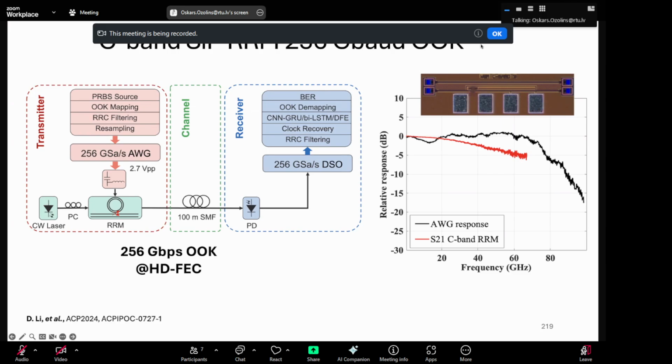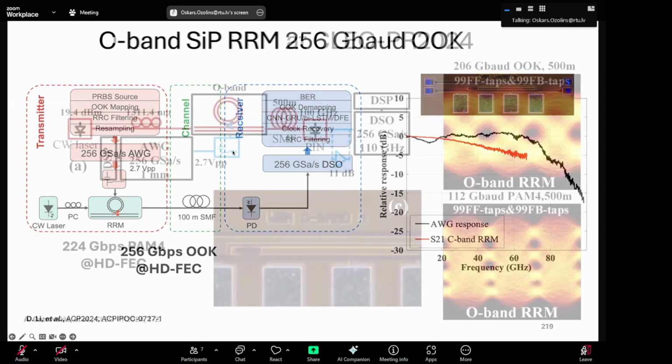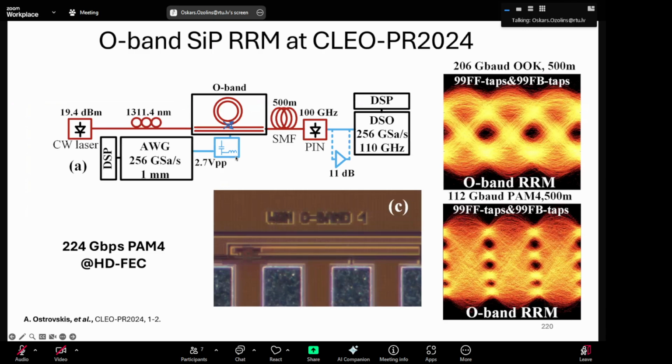On last week. So it's related to these silicon photonics micro-ring resonator modulators. And then there's also different bands of these modulators. I think the results we did look on was O band, which is 1310. In this case, 1311.4 nanometer laser wavelength, and in this band, the modulated bandwidth is smaller